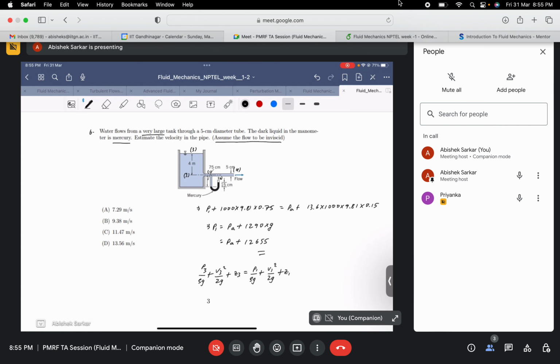That's again the issue, right? You cannot assume it to be 0. Even if the tank is large, this point is very close to the exit of the tank, and there would be a suction velocity that would suck the fluid out of the tank, and that's why the velocity at this point cannot be equal to 0. Okay, sir. So this is where I guess you have gone wrong, and it's actually a huge error. And again here, what do you know? I guess P is equal to PA. Then what is the velocity?